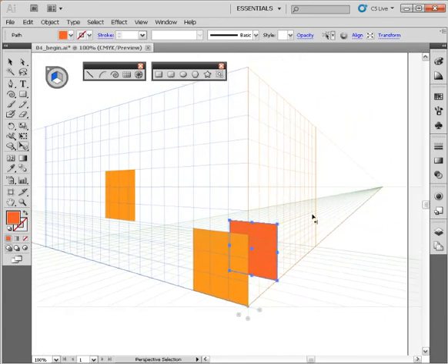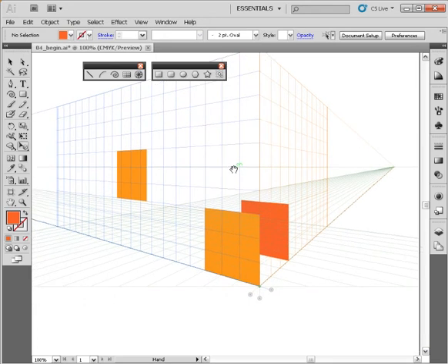So we've created that next side of our cube here, and I tell you what, let's deselect that here, and let's talk about creating this side of the cube right here that goes on our right grid plane. Well, we could actually come up here and just select the right grid plane from our plane switching widget here and just draw it right in there, or we could make a copy of this one and move it from this left grid plane to the right grid plane.